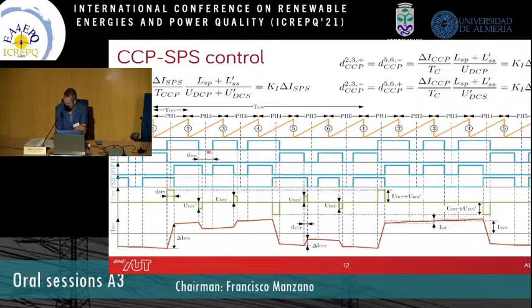But this time, we are continuously doing this. I mean, if we don't want to change the current, then we short both sides of the transformer for a fixed amount of time. But if we want to change the current, we just short the transformer on one side for a different amount of time, so we can create a current change as well. The advantage of this is that the dead time problems can be mitigated more easily, and also now the controller can run continuously, so we can do switching actions even when there are no load transients.